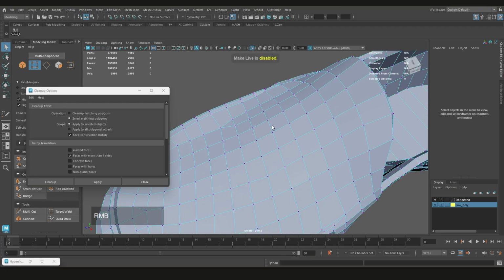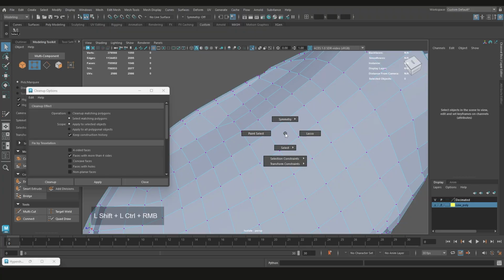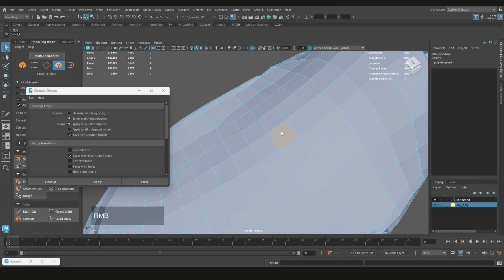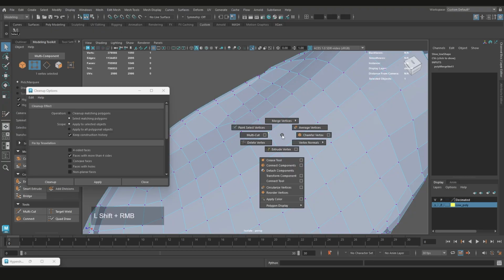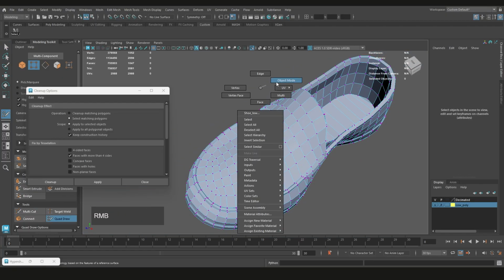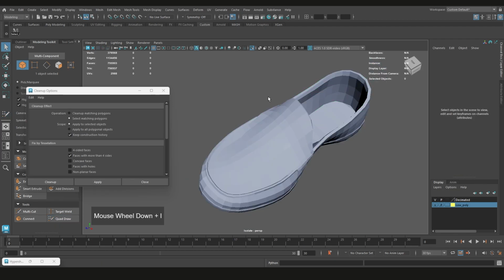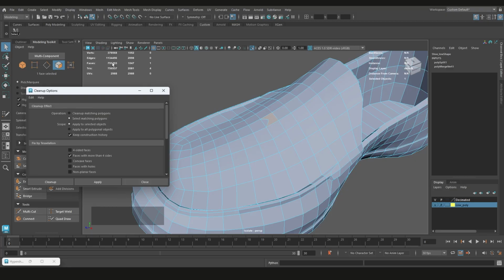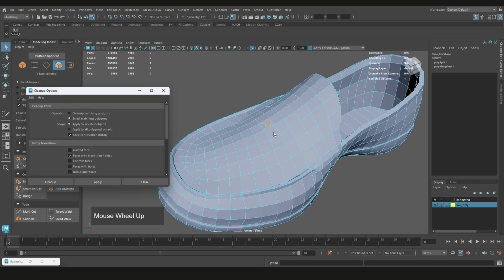And let's go to Vertex. And let's just cut this here, multi-cut. So we have a few random vertices. So we press enter, get out of that mode there, object mode. All right. So now if we go to cleanup and say apply, it's going to show you, oh, here's something here, and it'll tell you faces have been selected, and that's what's going on there.